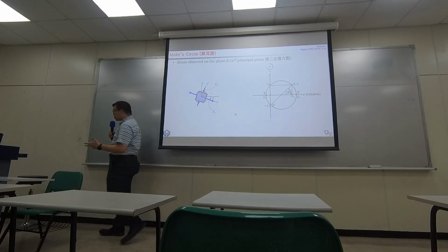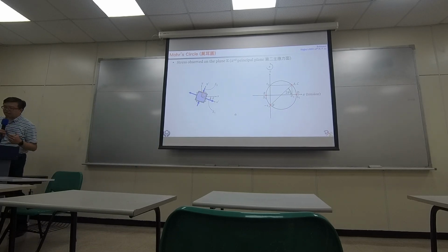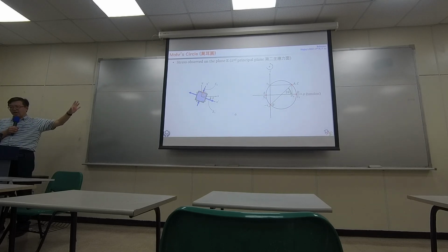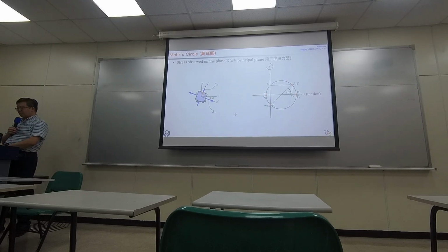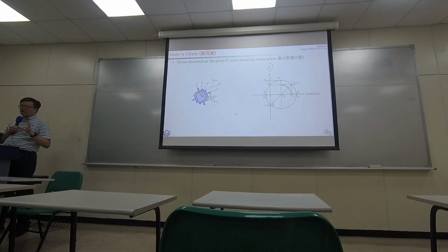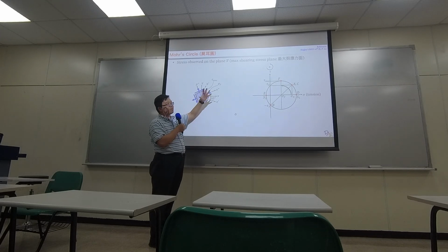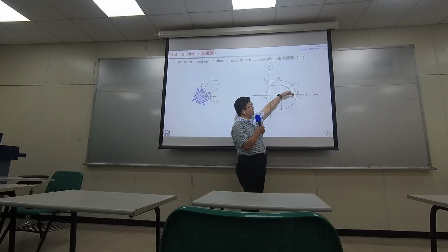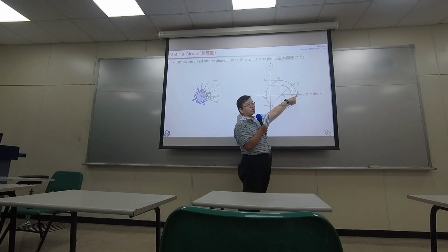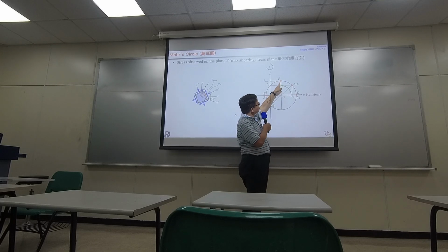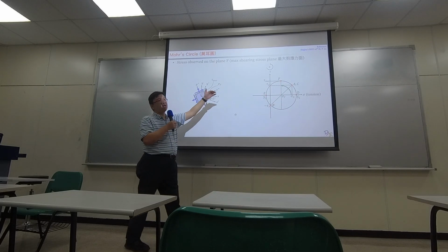Okay. And also, we also care about what is the orientation where we will be carrying the largest shearing stress. So based on this x prime, y prime coordinate, if I rotate the coordinate by 45 degrees, which means in the Mohr circle, we will be making a 90-degree turn from the principal stress, we will move on to a new point F right here. This is the position that we have the largest shearing stress.